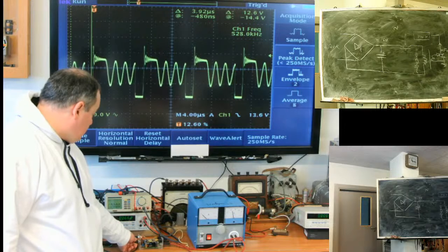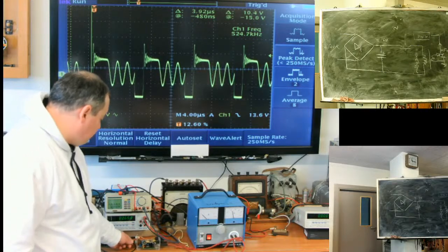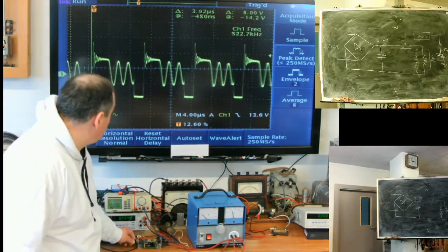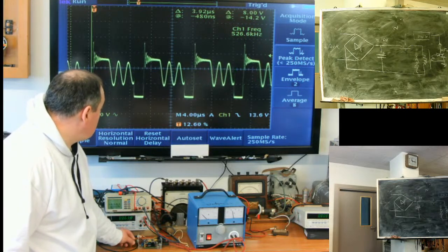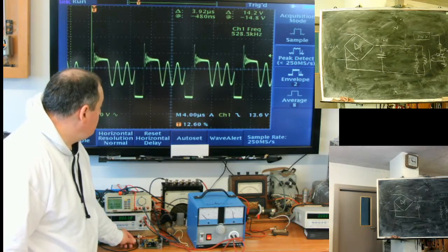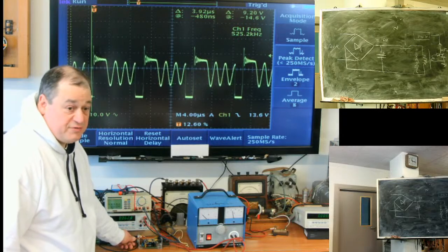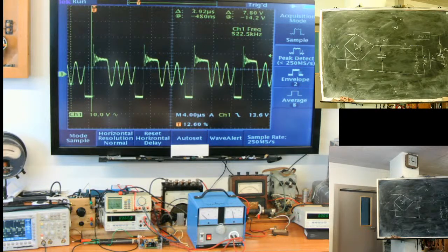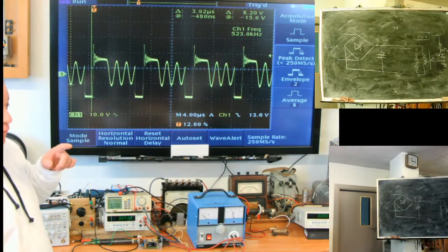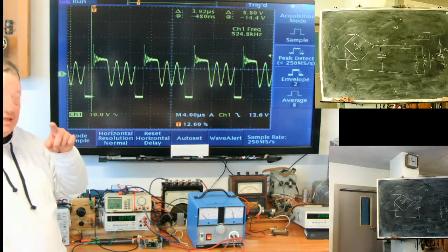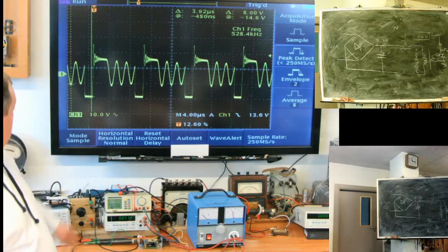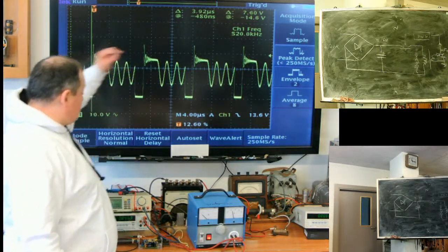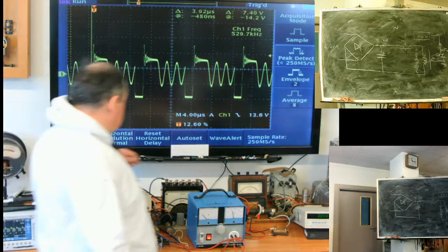Okay, take a look. I'm changing the load. Full load, half load. See how the pulse width changed? This thing is a kind of controller. What it does is charge the transformer primary coil and let it oscillate. This is so-called quasi-resonance.